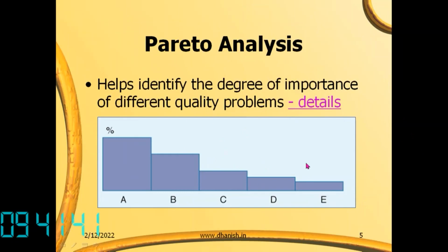So what problem to attack? At the final inspection station, you have identified various defects. Which defect should be attacked first? You can start, okay, the highest number of defects obviously should be attacked first. But sometimes you can convert into terms of money. Some defects may not be very costly, and can be easily rectified. Then it is not so serious. But some defects are very costly, resulting in large scrap. Then it is more important. So you can convert it to money and then make a table like this, a graph like this.